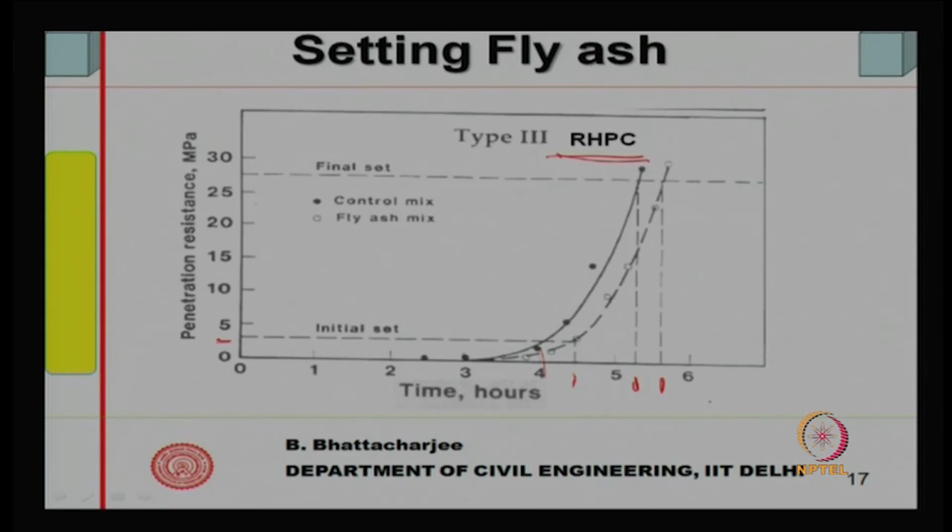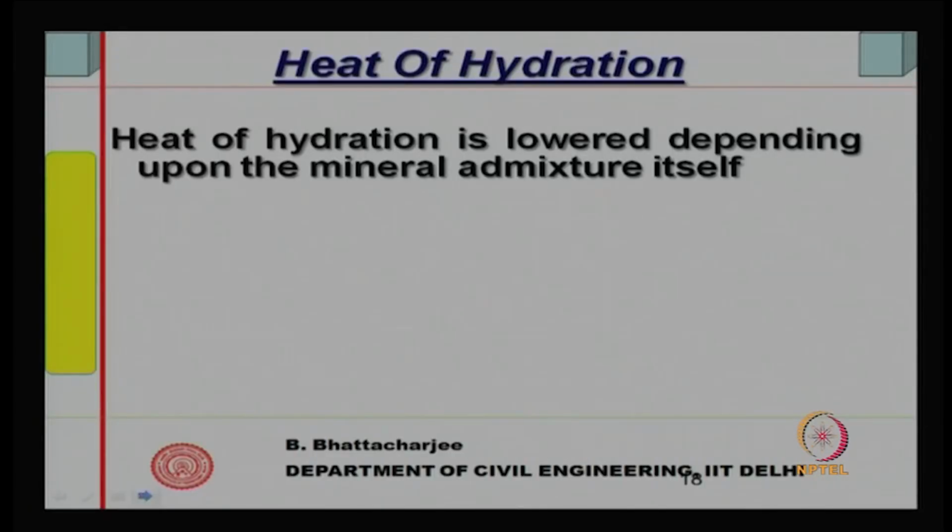So, the final setting time is within 10 hours and initial setting time is not less than 30 minutes. So, they do not shorten the initial setting time and do not elongate the final setting time too much to go beyond 10 hours, because normal cement has a final setting time much less than 10 hours. So, that is why they do not affect setting time adversely. The other issue is heat of hydration.